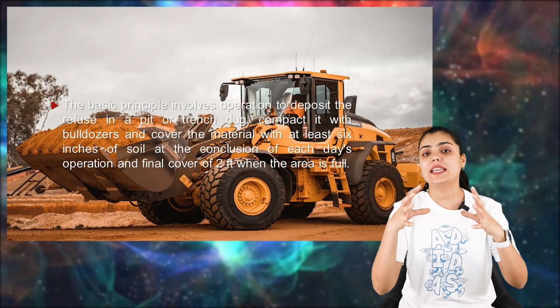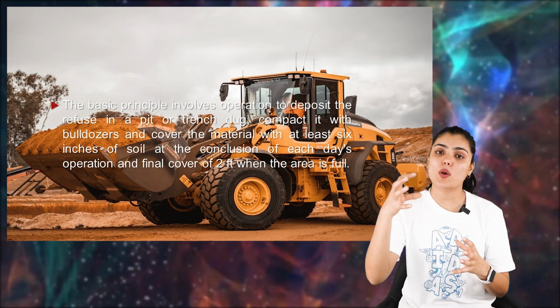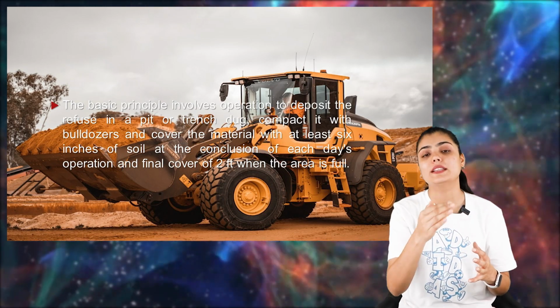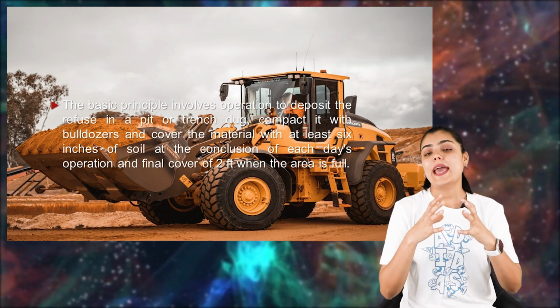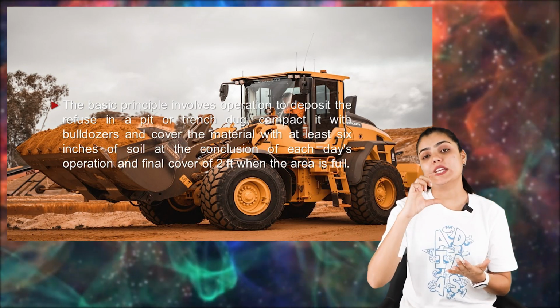So the basic principle in controlled tipping is to make sure that we dig the area so that it is large enough for us to dispose the waste materials or the garbage, and once it is disposed, it is covered by the dug out material. And in controlled tipping, the material is covered with at least 6 inches of soil. I hope you've got the basic idea of what controlled tipping is. Controlled tipping is also called a sanitary landfill.